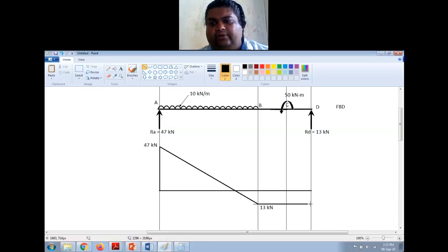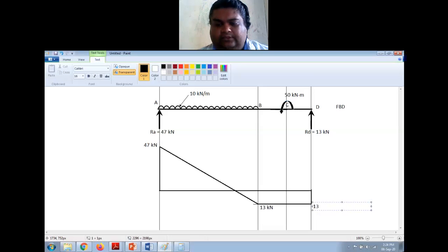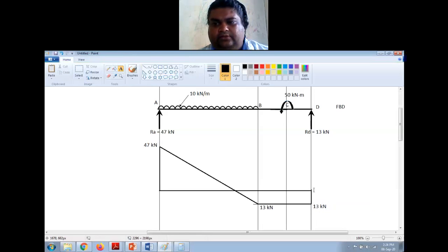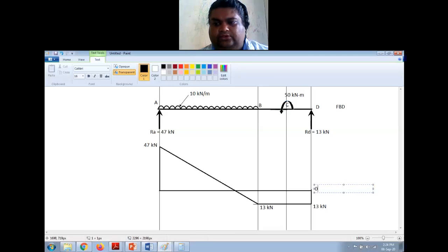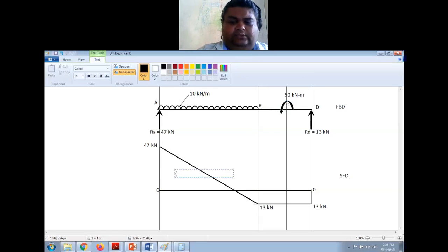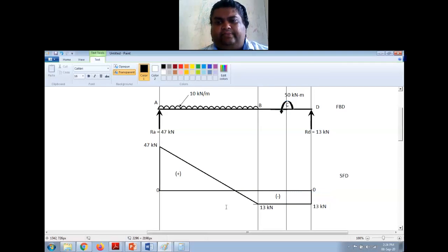Okay, so again I will draw another line from here to here, and I'll just write this is 13 kilonewton, this is 0, and this is also 0, right? And this is my SFD. You have to write all these things. This is positive, and you have to show this is negative, right?